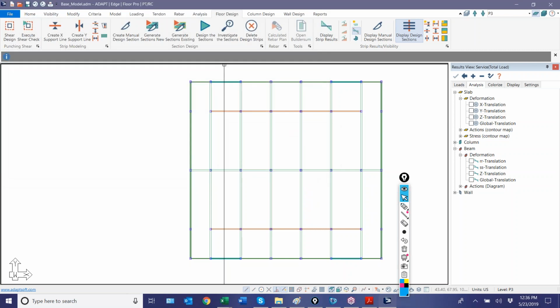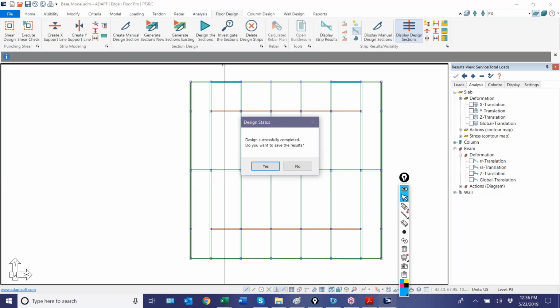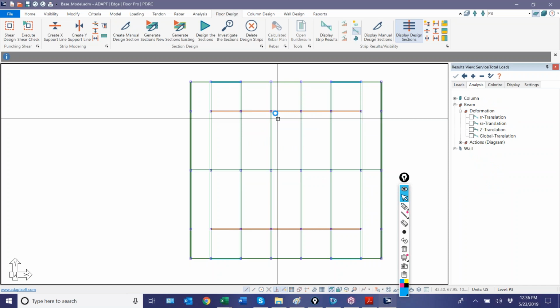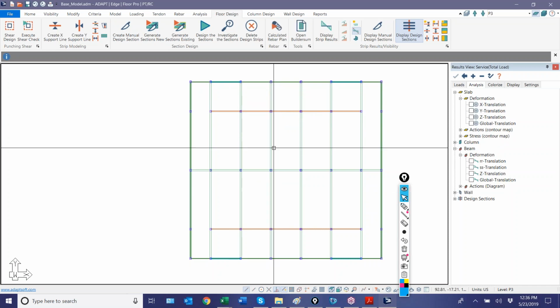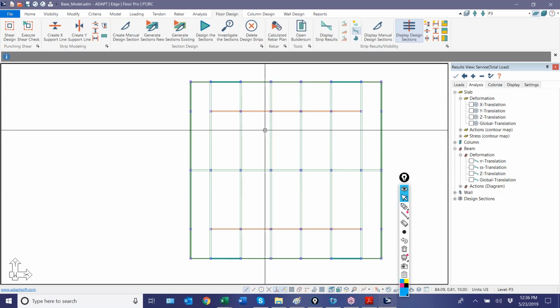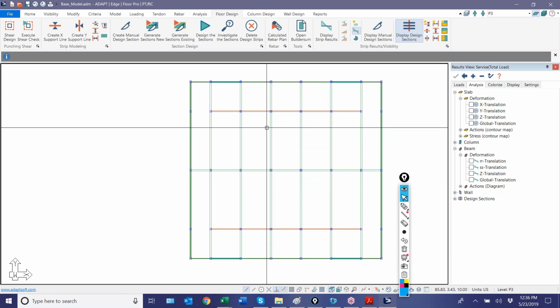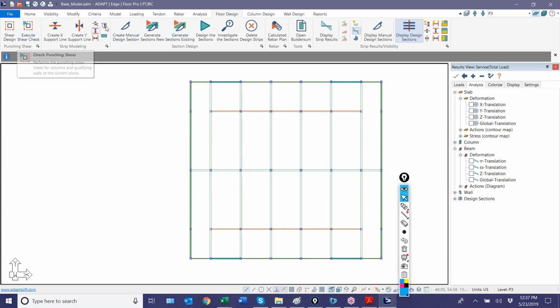So if we take instantaneous plus creep of 2, we get a factor of 3 times the max deflection, which is around 0.75. In this case, that likely would obviously work over a span of 60 feet for total deflection. There are ways to predict that more closely in terms of generating cracked deflection and long-term deflection combinations in the combination input.